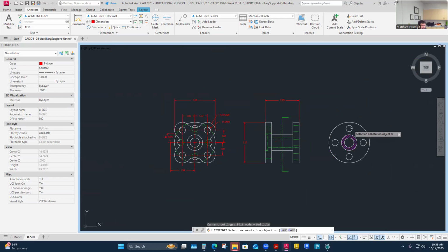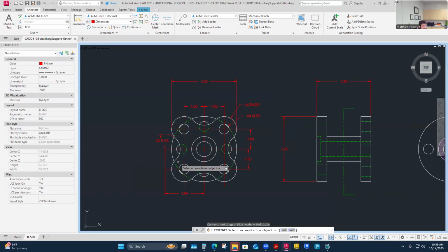I feel like I'm going to add their size over here though, just so it'll be more clear because their location will be over there. I don't feel like it's a double dimension either because it's a different part of this part. The X plate and the round plate are kind of two different parts, so I can kind of separate their sizing. Yeah, I don't feel like that's double dimensioning at all. So, and then its size and location is based off of those as well. So that this is doing double duty. Of course, I'm going to clean these up when I get to the end.